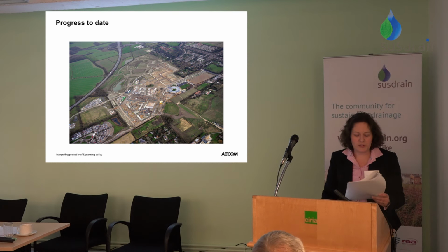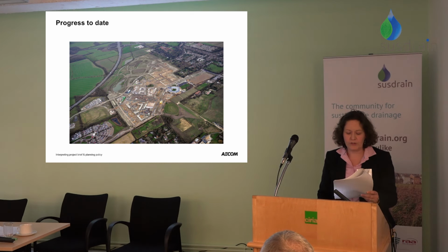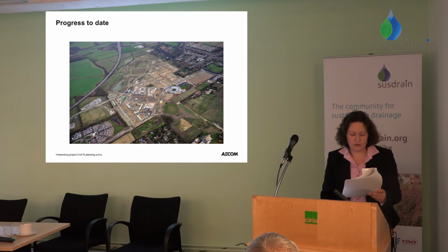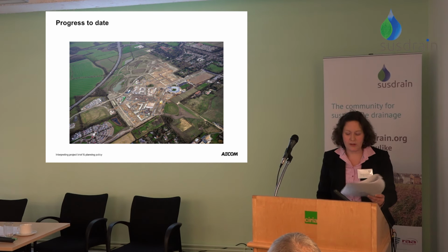In response to planning policy and comments from the EA and the City Council, commitments were given that the main surface water drainage infrastructure would be constructed in advance of any discharge being permitted from a plot into the drainage network, that runoff from each plot would be restricted to the rates specified in the drainage strategy during the construction phase, and that the construction of the Washpit Brook relief channel and the main Phase 1 surface water network and retention lagoon will take place as part of the first phase of the works to ensure that pollution control protection and attenuation provision was in place for the whole of the Phase 1 development. This photo shows how the university is honouring those commitments.